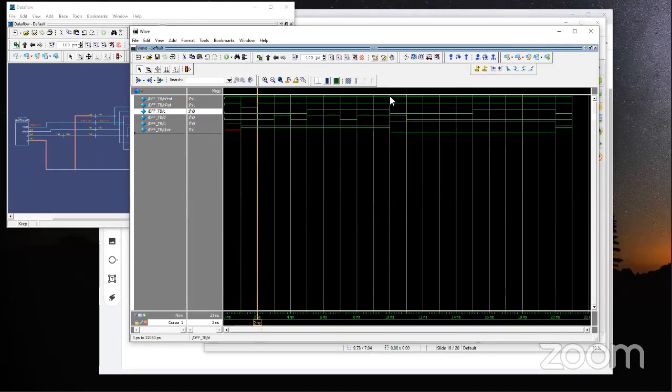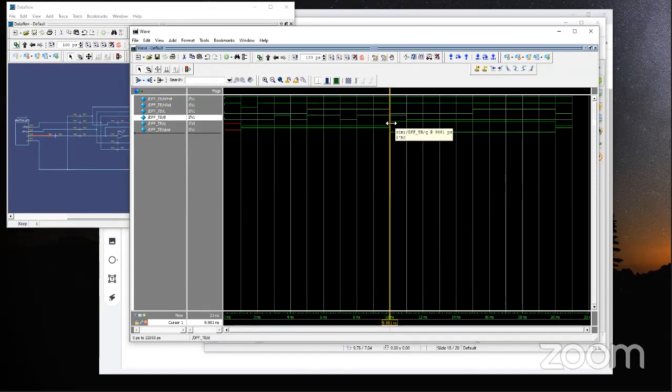Only at the point when the clock signal goes down from 1 to 0, at that point your D is at logic 1, and that's what Q followed immediately after that point. Immediately after that point, Q becomes 1.